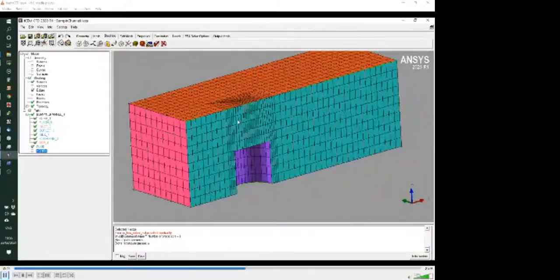We've noticed, for example, that if you were to calculate a CFD solution for a simple three-dimensional wing, if you use a block structured hexahedral mesh like this, you can get wonderfully accurate results with only about 120,000 grid cells. That's very little. You can easily solve that on a laptop computer, and the answers will be very, very close to any kind of theoretical experimental value.